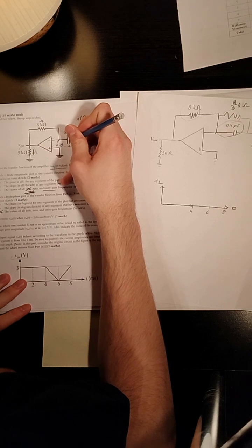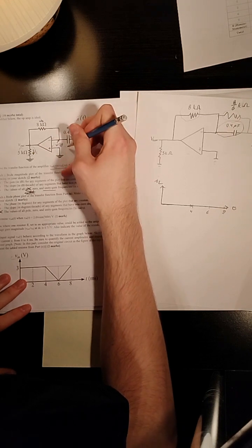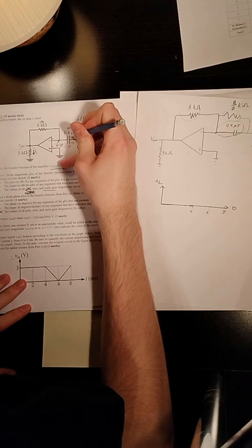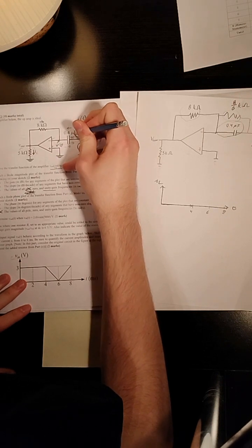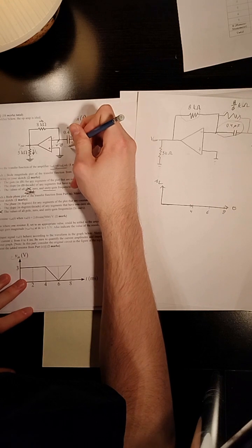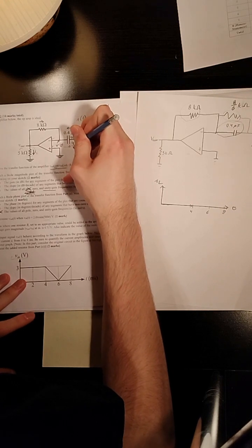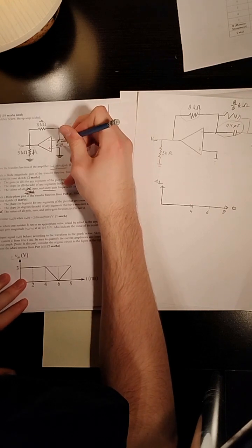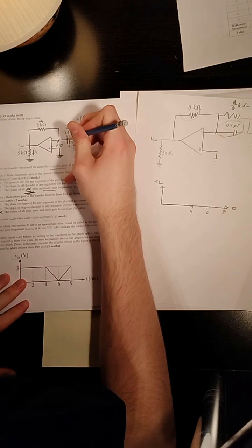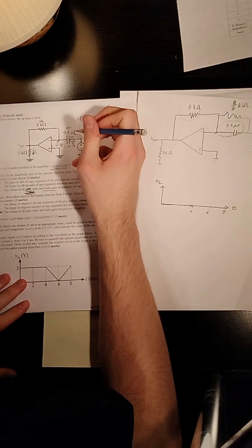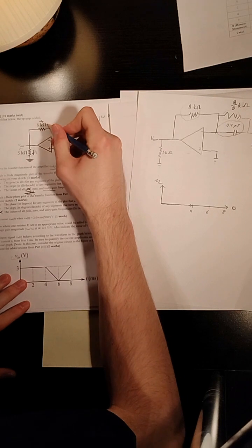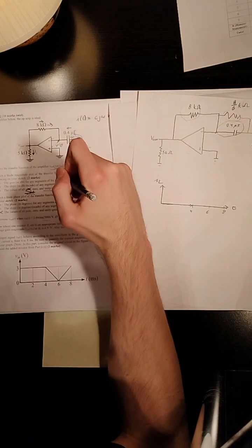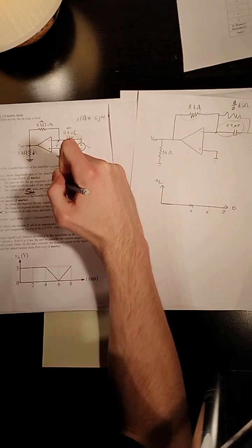If the voltage in the capacitor is built up by putting charges from the voltage source there, then the voltage can be taken down again by removing those charges. So you would get a positive current flow going this way, which means current would flow this way across the 8 kiloohm resistor as well.